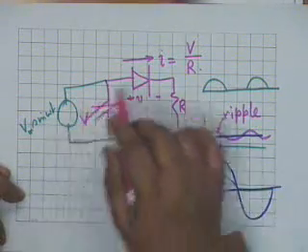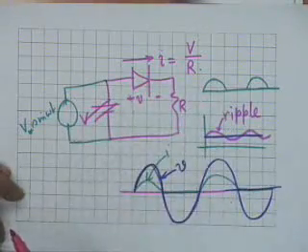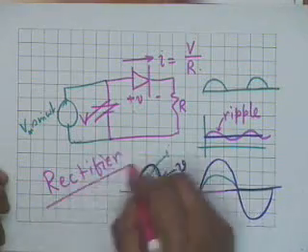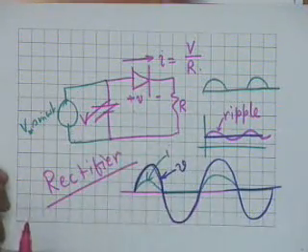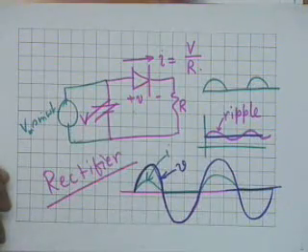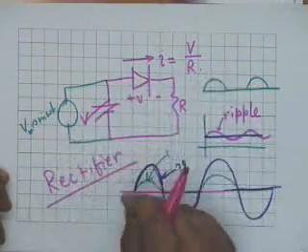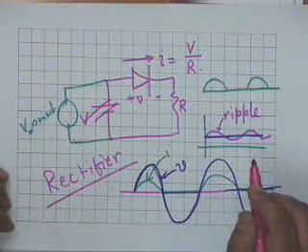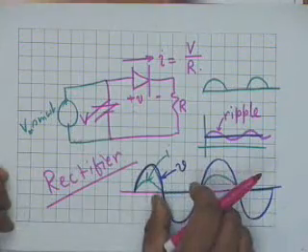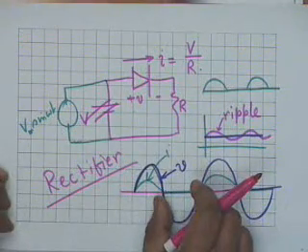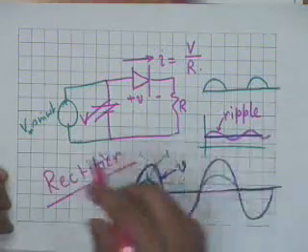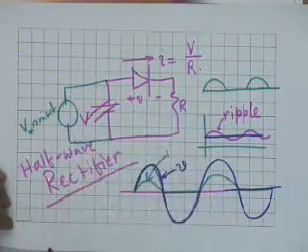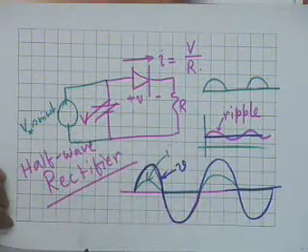Now, a diode used in this manner is called a rectifier. It rectifies the AC voltage to a unidirectional voltage, alright. A diode connected like this, since it converts only half of the wave, the other half goes waste. We are not doing anything to this. The other half is simply blocked, and therefore this is called a half wave rectifier. A half wave rectifier. Alright.